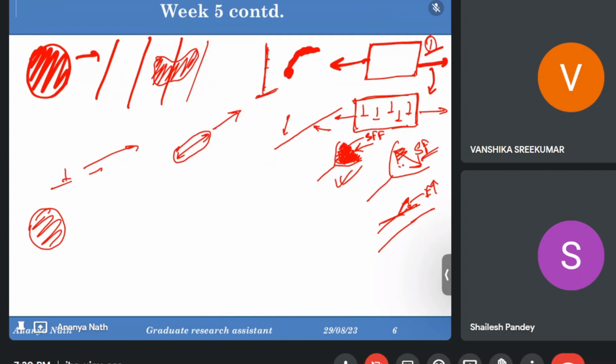If you are appearing for some interview or going for some test or examination, you'll face this type of question: what is quenching, annealing and normalizing, and what is the difference between the three. In all the cases, we go up to the recrystallization temperature or whatever temperature we want, but we cool it down differently. For quenching, it's water or oil cooling, fast cooling. For normalizing, it's slow cooling in the air. In annealing, it's the slowest cooling, in the furnace.